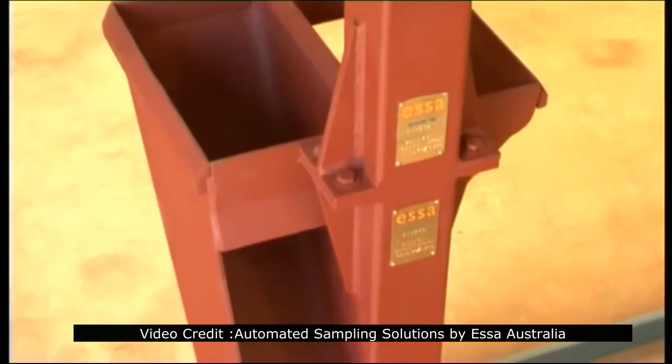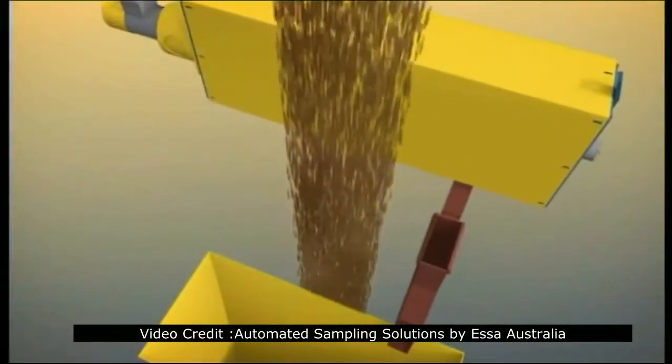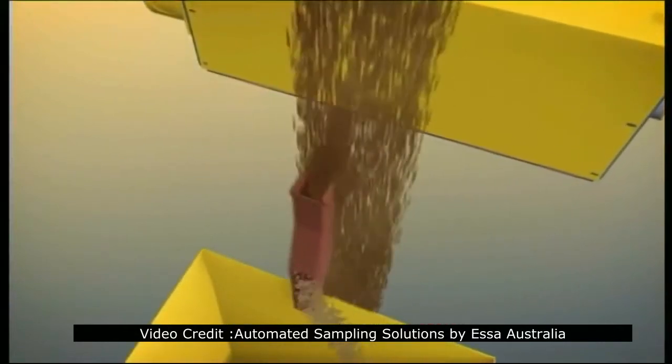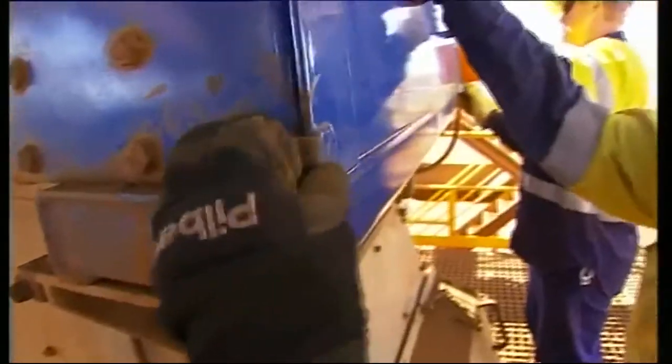Design of the primary and secondary cutters is crucial to achieving accurate and representative samples. All particles must have an equal opportunity of being sampled without any loss or contamination. Taking a sample from a falling stream is the preferred way to adhere to these fundamental sampling principles.